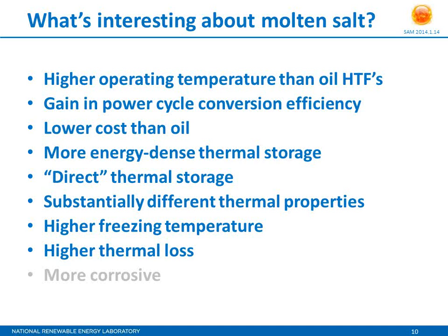The stability limit for, say, Therminol is around 400 degrees Celsius, whereas molten salts can typically operate up to 550, 600 Celsius, which allows you to run a more efficient power cycle. And so you have that potential carrot that you might be chasing after.